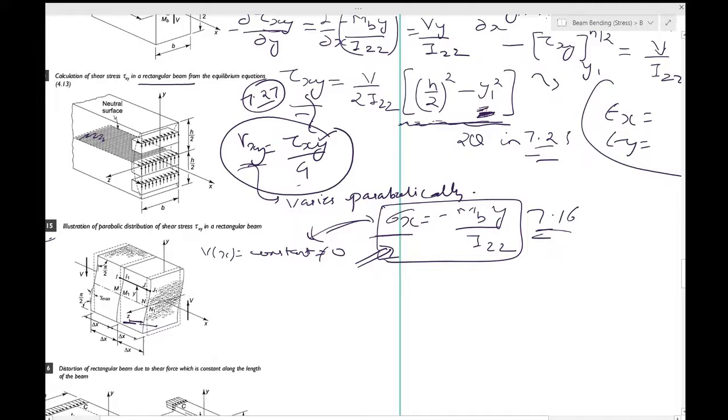So that's the reason. You have to see this from Hooke's law. Look at the formula of epsilon x and see how it is related to the other stress terms. Many of those terms will be 0, and this is how you can say, because ij is of the same length as i1 j1, the normal strain in the x direction should be 0, and hence the normal stress due to the presence of the shear force gives no extra contribution.